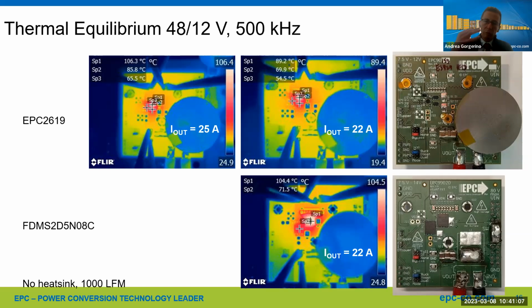And switching faster, as I mentioned already, means you're fighting against all the circuit parasitics. If you lay out your board, in order of priority there are basically three areas. It's a 3-pin terminal, so there are three things you've got to think about in terms of inductances: the source inductance, the drain inductance, and the gate inductance. The most important one is the source inductance. That's the common source inductance, the inductance that is in common between the gate loop and the power loop. The reason it's important is that during the transients you have this high di/dt in the inductance, and it's subtracting voltage from your gate. So it's like having a higher gate resistor: you're slowing down your device. It effectively puts a limit on how fast you can switch.